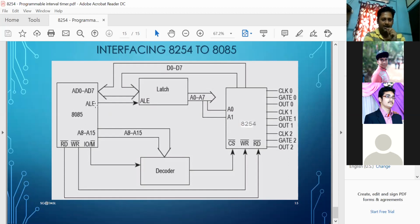Address latch enable: if the latch is enabled, at that time the address will be transferred. So if the ALE signal is high, then the latch is enabled, and the output from this latch will be address only, no data will be processed. And if the latch is disabled, that means data will be processed. So ALE is address latch enable. When the latch is enabled, only address will be transferred. When the latch is disabled, just opposite to this one, what will be transferred? Data.